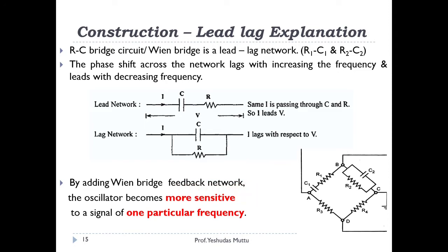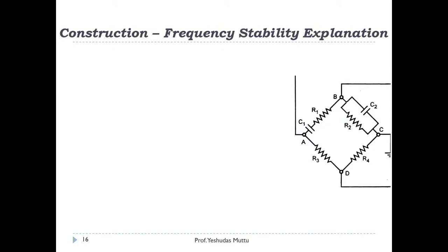Okay, we are going to see now. At this particular frequency, what happens is that the phase shift is 0. Okay, and if the phase shift is 0, I say that my bridge is balanced. That is the most important thing whenever I deal with bridges. I require the balancing condition. So I will say that at one particular frequency the phase shift is 0, and whenever this happens, that time I would say that my bridge is balanced.